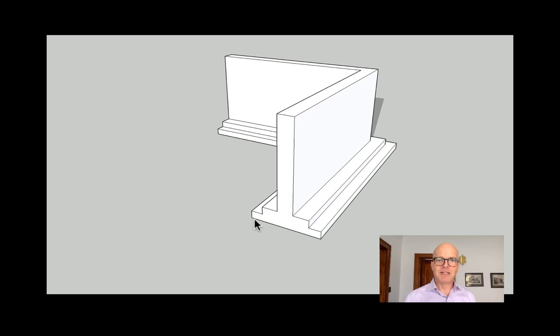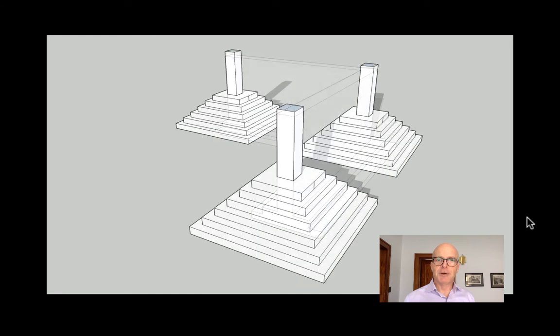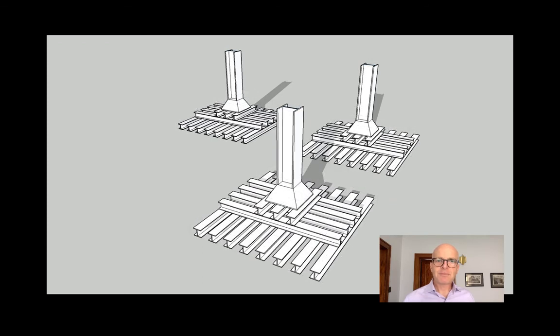So that load is basically getting spread over a slightly wider area of soil below. Those stone pyramids were designed basically to spread the load out. And in stone, they're worried, of course, about shear. If you build just a flat floor of stone, a column is going to go right through it. So they would build pyramids to literally take the shear from the column and spread it out over successive terraces of stone. The advantage to the grillage foundations is that you basically bought space in the basement.